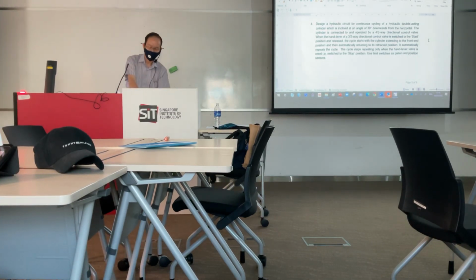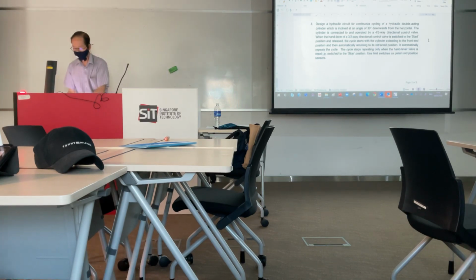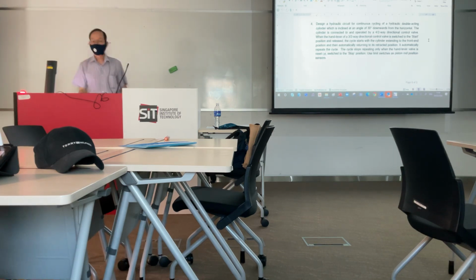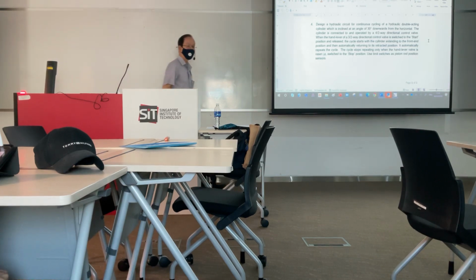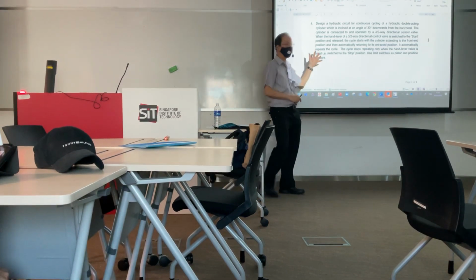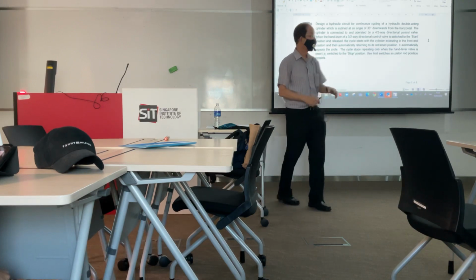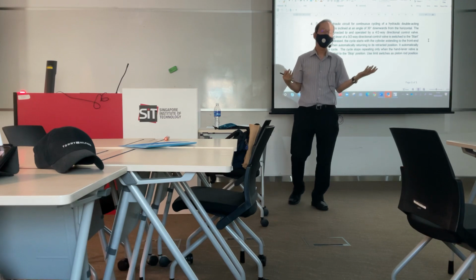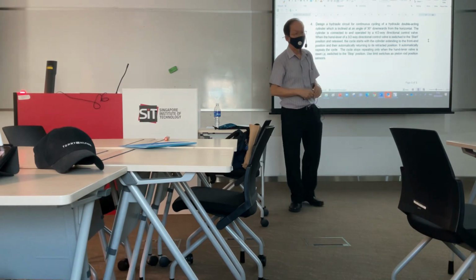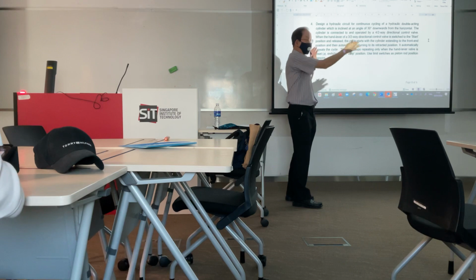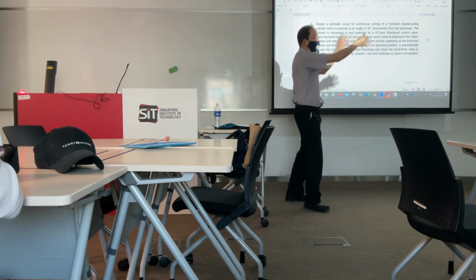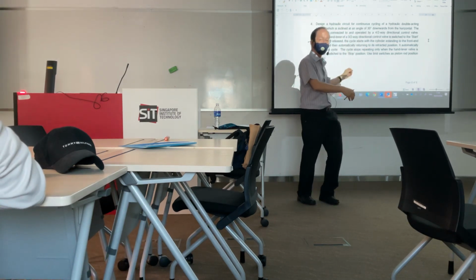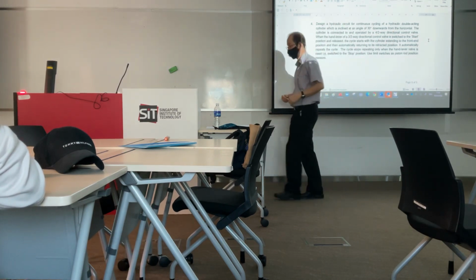Okay, so what's the first thing you do then? Double acting cylinder. If you're a good designer, you will only choose the minimum components to satisfy the requirement, yet it works safely. You don't want to add too many additional components which are actually redundant. Then you add more cost to the company, because the company may not want just one circuit; they may have this repeated 10 times. So adding one component means 10 of the same components.